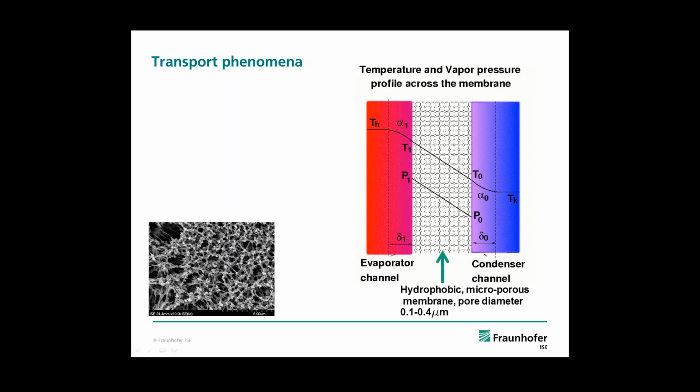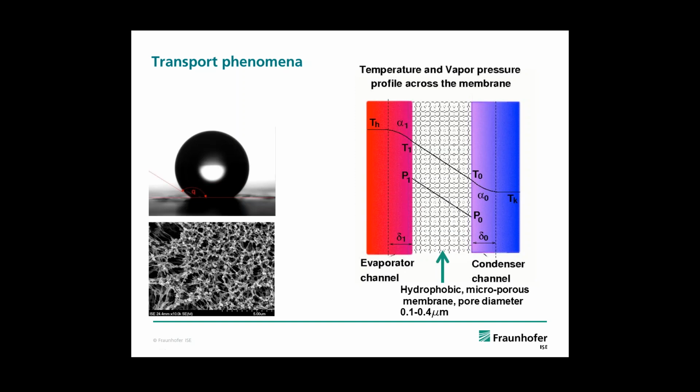One more question as well is, how did you know the water quality of the project sites that were chosen for the example plants? Yeah, this is very important. So we have to analyze, we have to get samples. Previous to any design, this is the most important factor, to analyze the quality of the raw water. So you have to make an analysis of the water. Very good. The main salts and also the salinity itself.